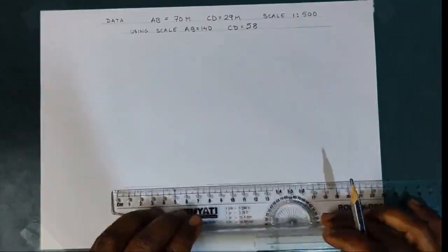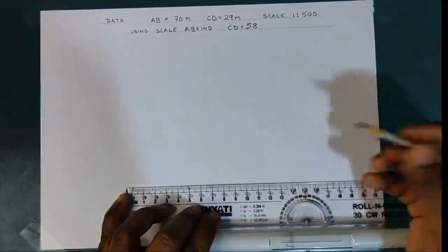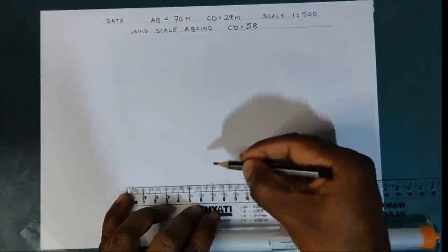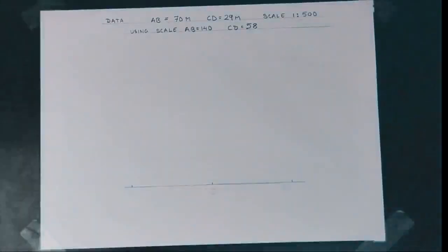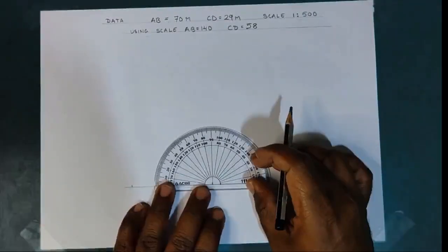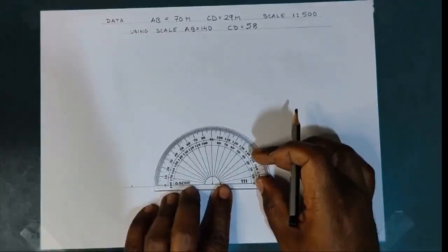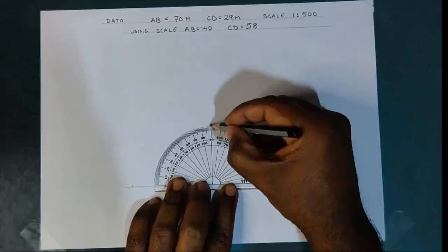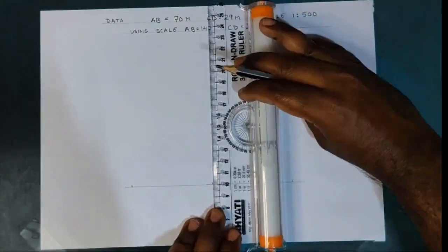So we start with first drawing a horizontal and taking the length AB equal to 140 mm long, and also I mark the center point. About the center point, I draw a vertical so that I can draw the height of the parabola axis.